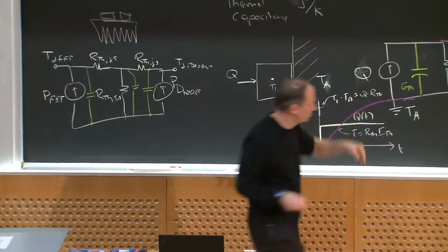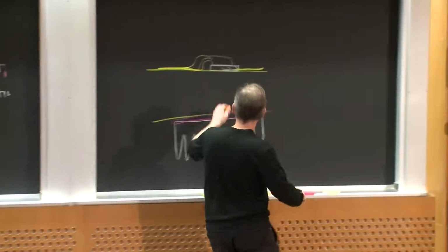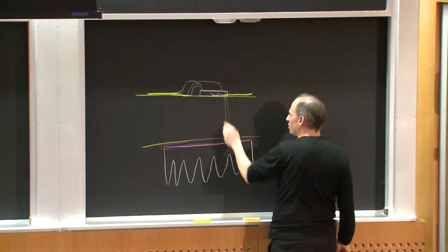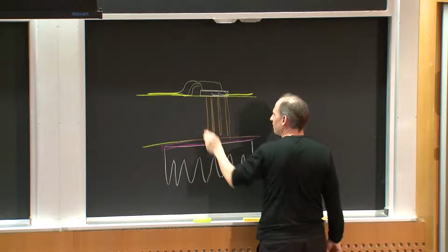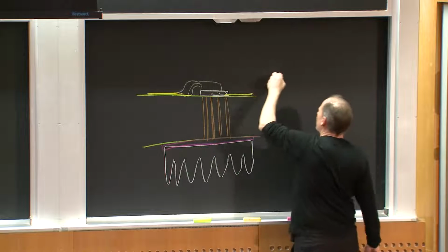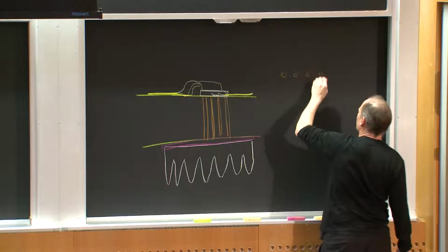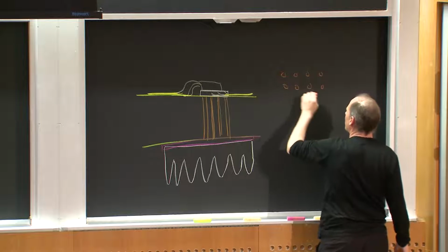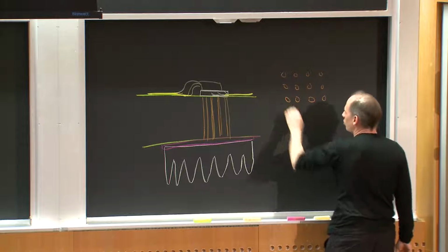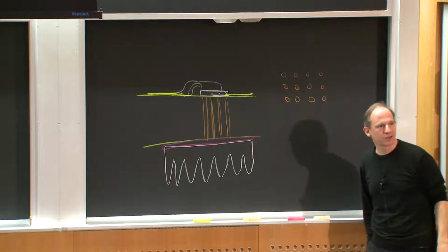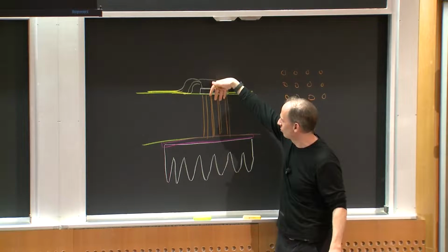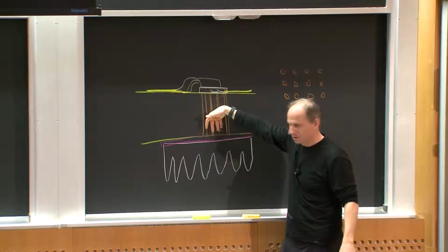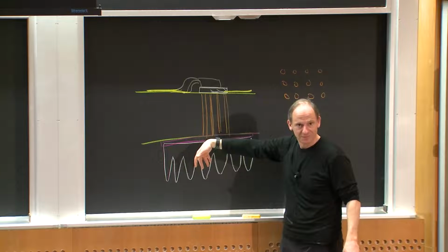So one of the things you often do is put thermal vias in the board. If I looked at this from the side, you'll drill a bunch of holes through the board. You'll put holes in the board like this, and you'll put what's known as a via farm. Okay? If I looked straight down on top of it, you'd see a bunch of holes drilled in the board like this. Okay? Why? Because those holes will then be plated with copper, which is a good thermal conductor, and it'll help me transfer heat down through the board to the interface material to the heatsink.